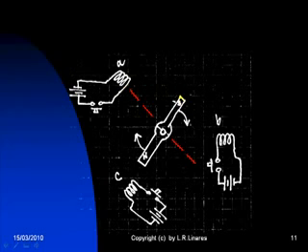Now when the bar is halfway between coils A and B, I push the button of coil B. Coil B becomes an electromagnet, and now the bar will try to align itself with coil B, like so. When that bar is about to be aligned with coil B, I let go of the push button and let inertia carry the bar over halfway between coils B and C.